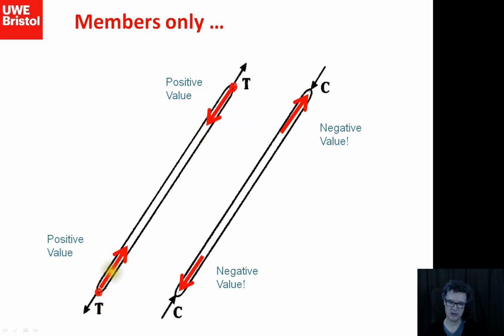And you can see that those forces there seem to be pointing inwards of the member. If, however, we were squashing the member, what would end up happening is that we would have internal forces trying to oppose that squashing, and those internal forces would be pointing towards the joints. So we would actually be finding values which are pointing away from the joints, but they would have a negative value.